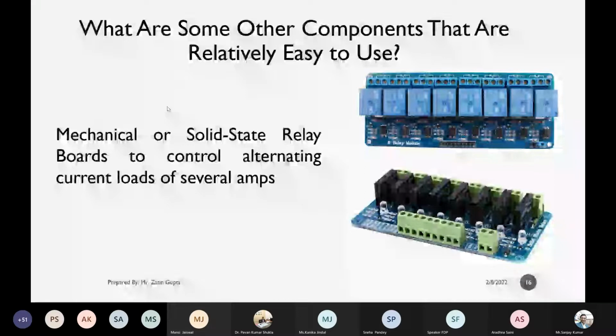If the garage is automated using Arduino and relay, then that person can send the command from his mobile if the system is IoT enabled. Else, he can send the command using other components like a keypad or Bluetooth after reaching near the garage, and then control it from that component.